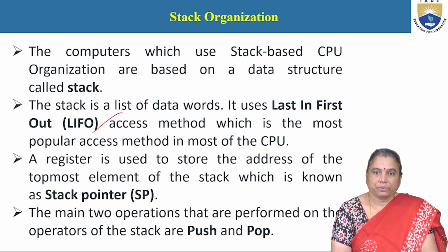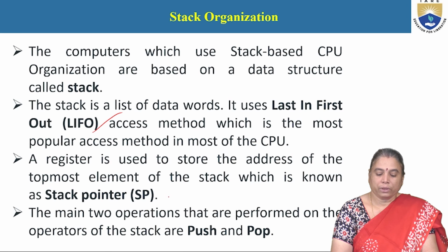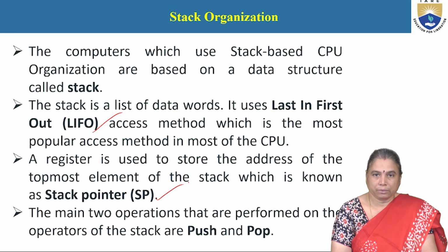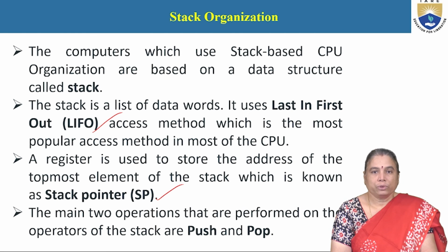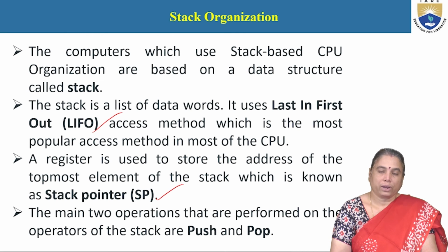So this is the best and most efficient way of storing the return addresses of the subroutine. The register used to store the address of the topmost element of the stack is called the stack pointer, SP. And two operations can be performed on the stack data structure, that is push and pop. Push is used to insert an element in the stack. Pop is used to retrieve an element from the stack.